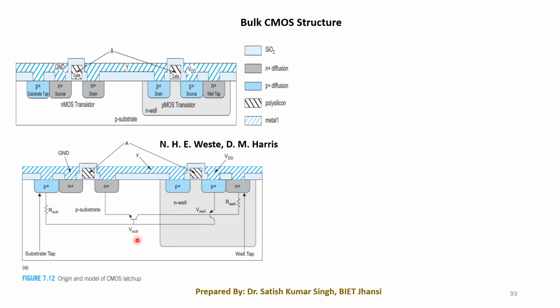There may be certain parasitic elements or parasitic circuits that exist within this device. Because these two transistors are not isolated electrically, there is a chance that the circuit may form a low resistance path. Because of the existence of this type of parasitic element, the functionality that we want from this device is going to be affected.